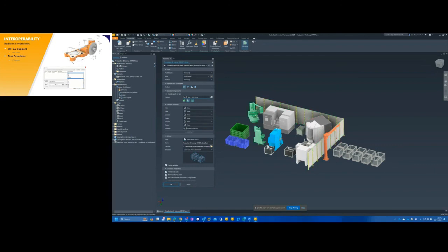So again, some of this stuff still has a lot of detail. So I've created a model state view inside of Inventor to remove some of the detail on each of these top level components. I'm just going to switch to that view, which is called medium. And you'll see when I pick that view, the Inventor model simplifies down a bit, right? Some of the features are gone, and it's a more simplified view that I'm now able to bring in.